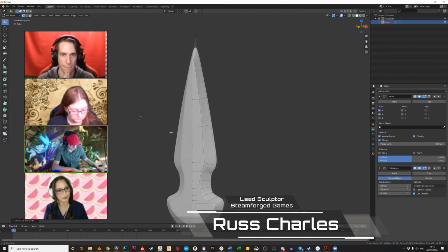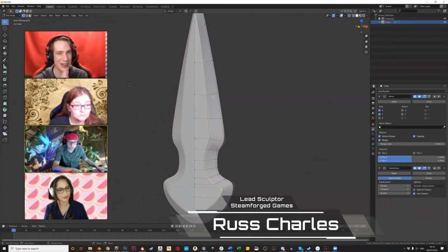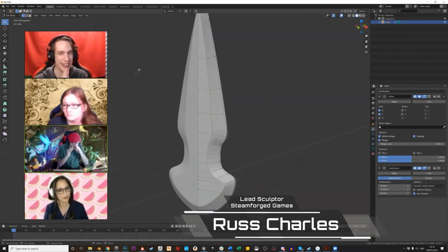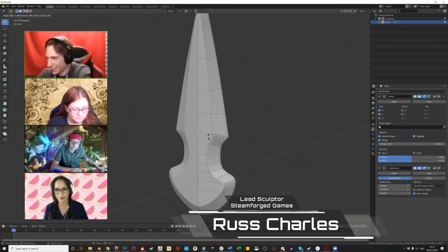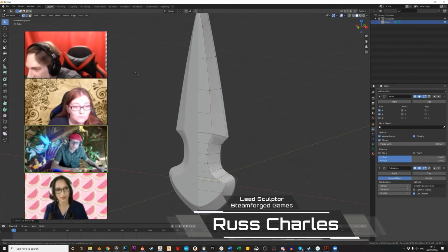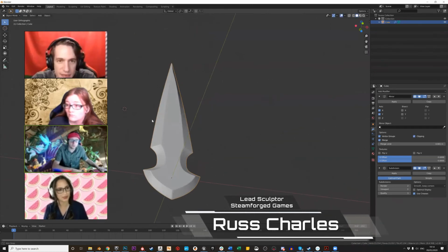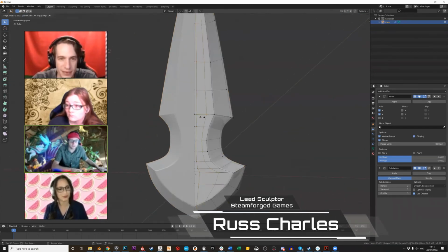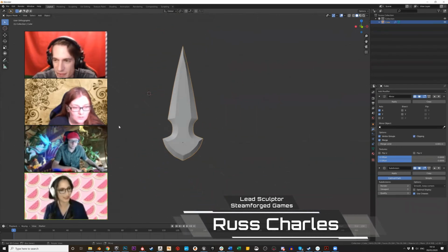I'm going to do the same thing again and bring it back towards the inner edge, and you can see that edge sharpening. You can now see those edges have crisped up, because the closer together we put these loops, the smaller and tighter it tries to make the polygons. So this method of adding extra loops is going to let us crisp and sharpen all of our key edges. Let me just show you the shape target that we're aiming for. We're trying to create something that looks a little like this. Excellent.